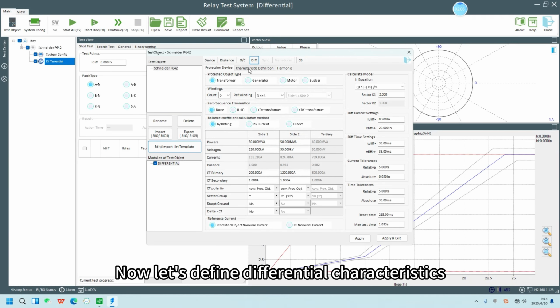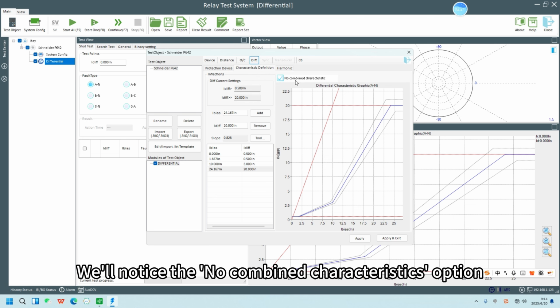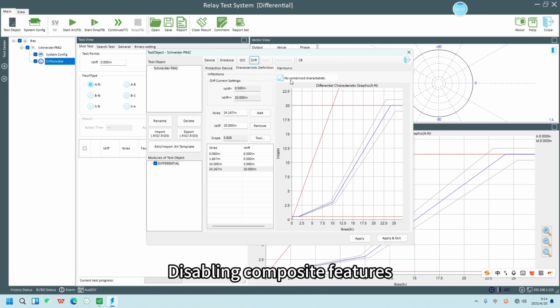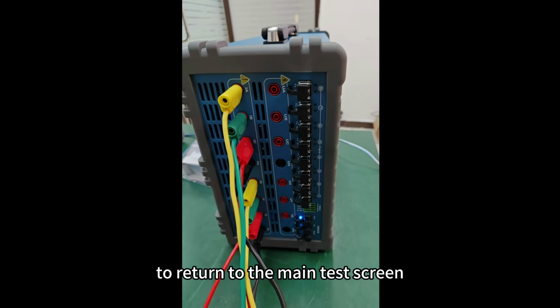Now let's define differential characteristics, the heart of this test. We'll add, delete, or modify current, restraint, and curve settings using our tools. We'll notice the No Combined Characteristics option. Activate this because during normal operation, protection relays filter out large differential currents. Disabling composite features prevents healthy phases from false tripping during tests. Once configured, simply apply and exit to return to the main test screen.